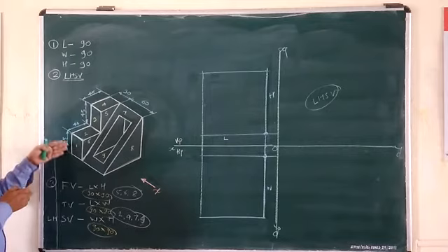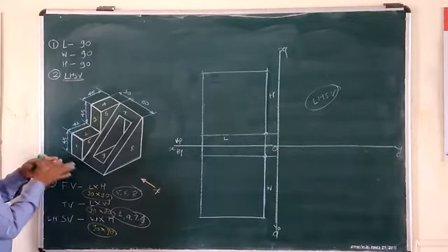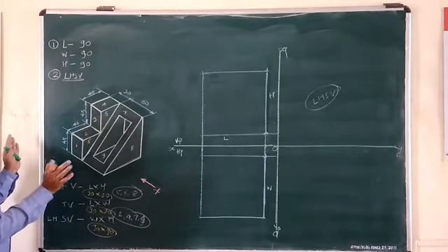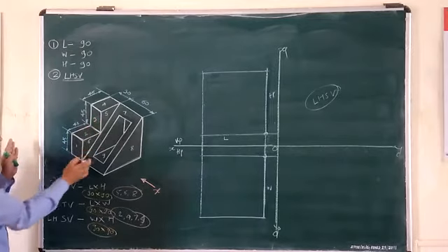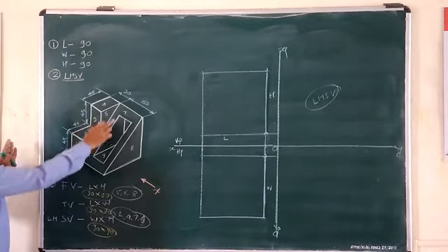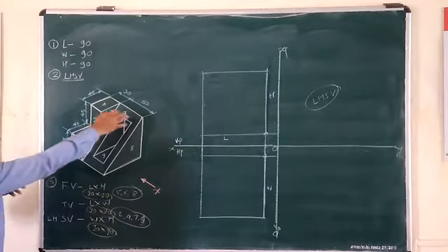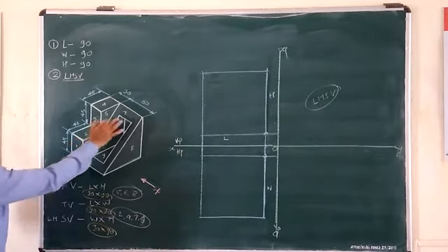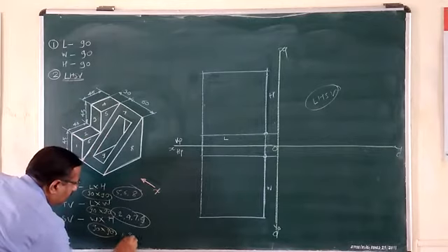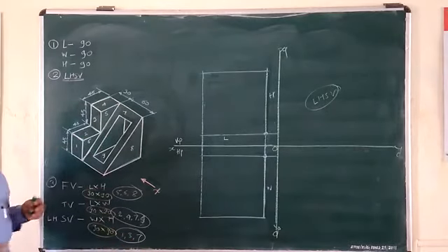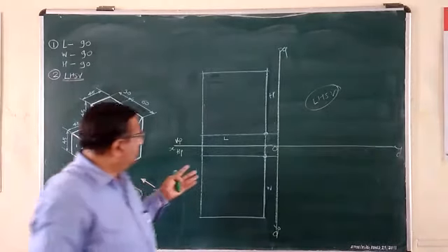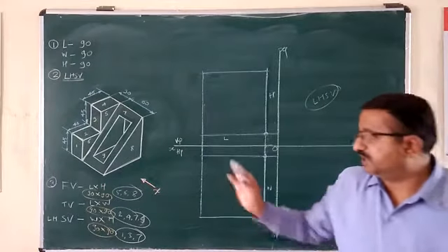Face number 1 is vertical, 3 is here. This slant face number 7 is also there. Nothing else. Only 1, 3 and 7 is the slant surface, and there is a hole. That's why only this rectangular vertical strip will appear on surface number 7. So 1, 3 and 7 are the prominent faces that will be visible to the observer while observing in the direction of left.